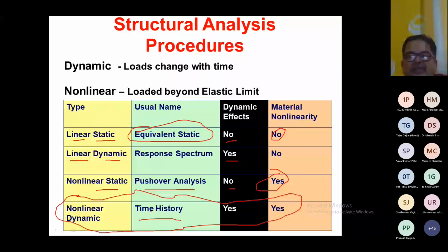When it's a 3000 degree of freedom system, your matrix size will be 3000 by 3000, and it is very difficult to analyze, right? So time history analysis gives you a better result as compared to others, but it is very time consuming, right? So therefore we go for certain simpler methods, which are very fast and easy to digest for most people, right?